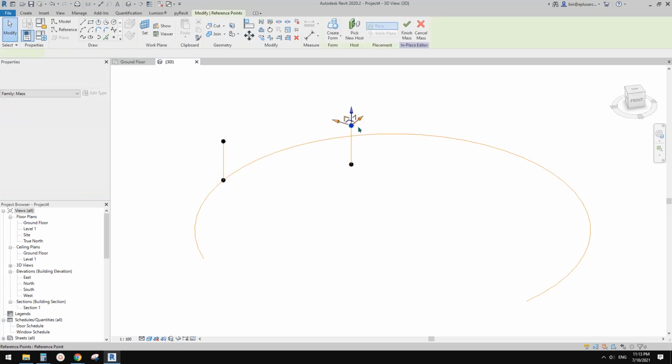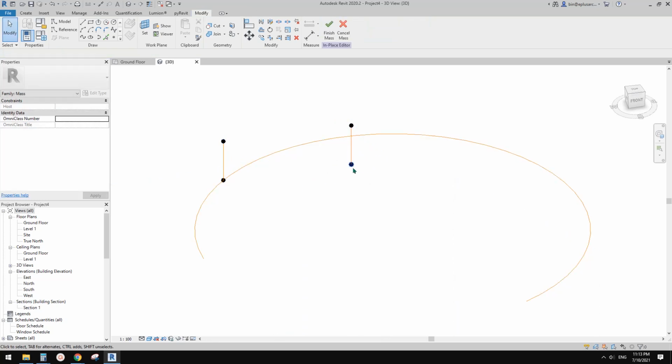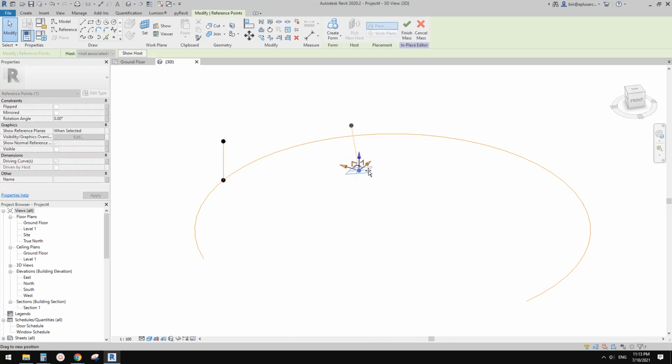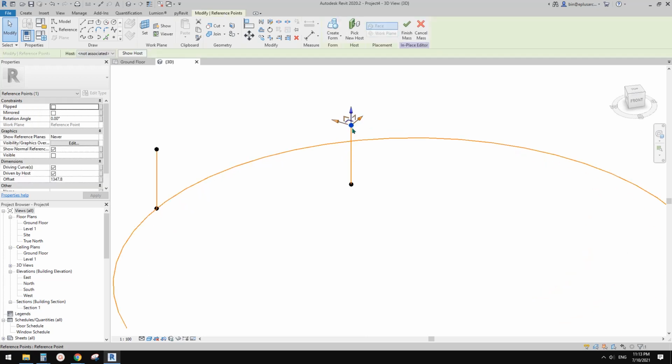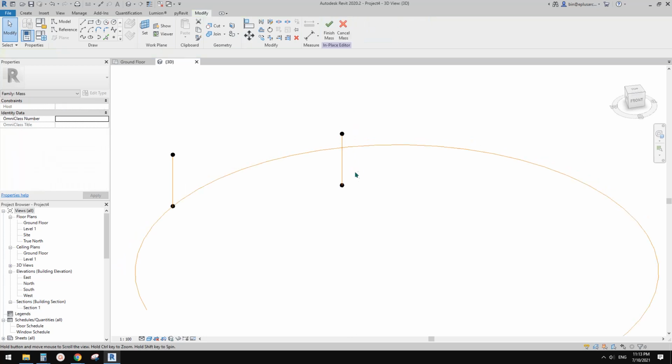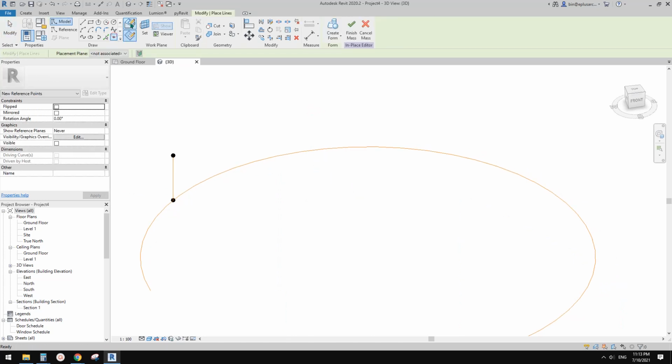I want to try because I want to, no, so it looks like once we create a spline, we won't be able to copy this and still have this point placed on the work plane of this point. So yeah, maybe we can do this. Let's just do it again. So just place another point. It's probably easier to do it this way.